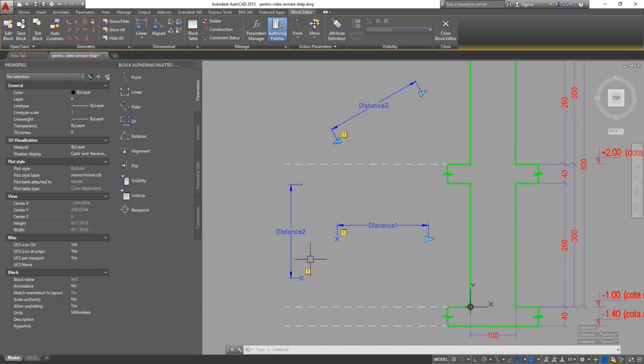No, it will still be in the block, it will still have actions, will still activate different parts of the drawing, but not with visible grips. That means you couldn't manipulate it in the properties tab outside the drawing, but only via Lisp command.